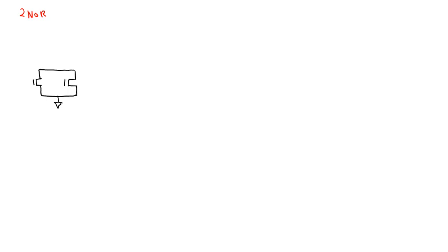And then, because we start from NMOS here, the PMOS side should have the opposite of parallel. So you need to have the PMOS in series. Okay.